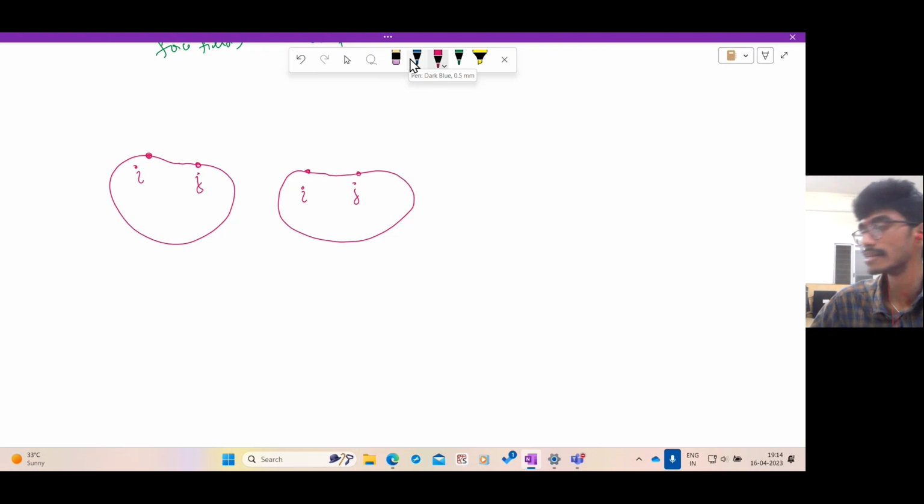And the body is subjected to some displacement field, right? So there will be a displacement here and here. But this can be thought of as a superposition. In one case, you hold this fixed and you allow ui alone. And in the other case, you hold this fixed and you allow uj alone. And you can superpose both.